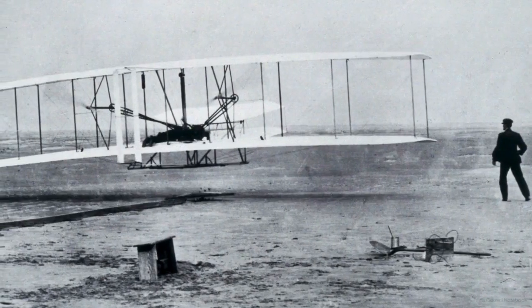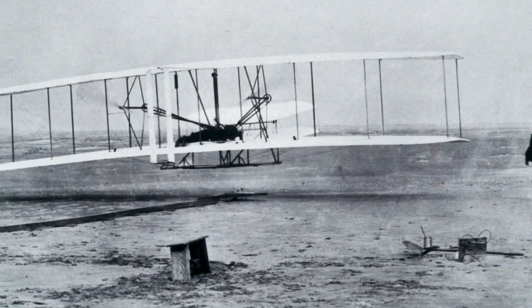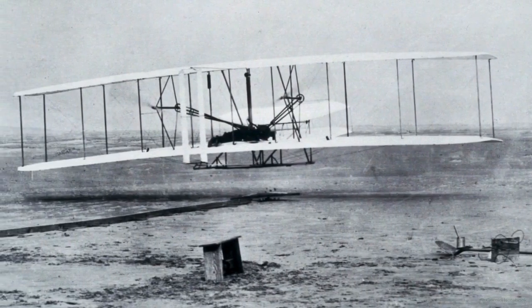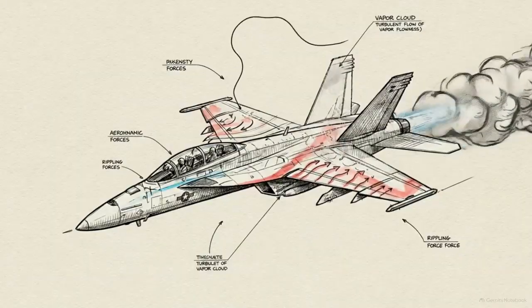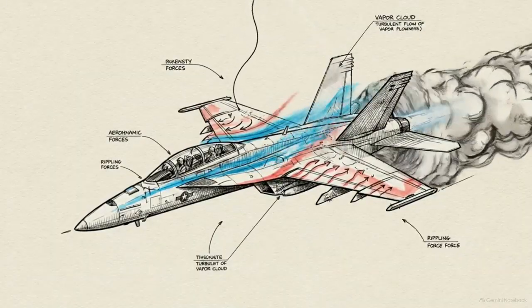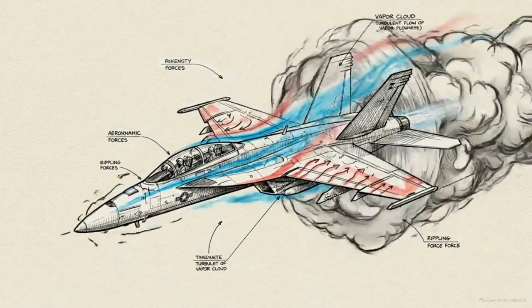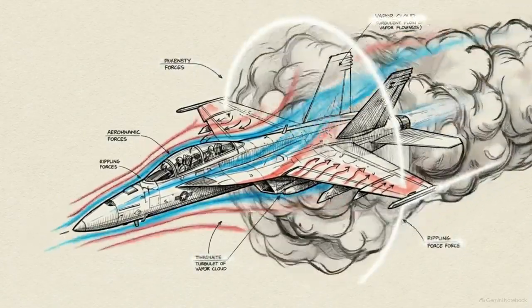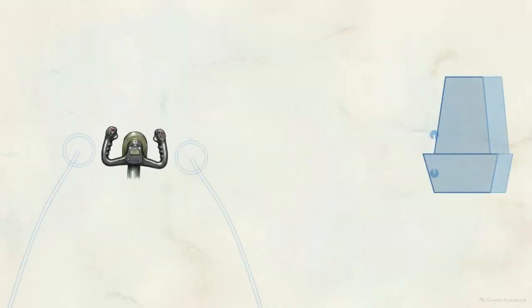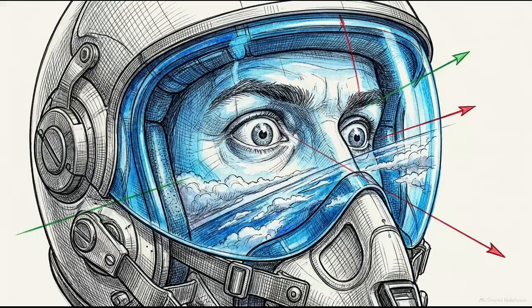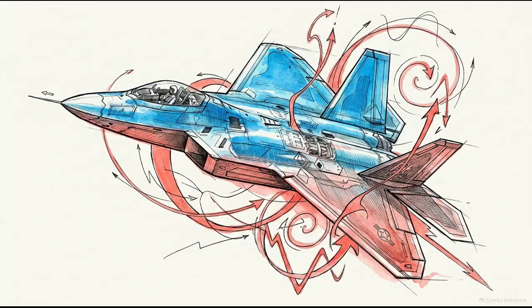In early, lightweight aircraft, this touch was a direct physical struggle, a literal battle against the wind hitting the wings and tail. As aircraft evolved in size and speed, engineers were forced to sever this direct mechanical link to protect pilots from the massive aerodynamic loads involved. This created a new engineering challenge: the need to artificially synthesize a physical control touch that is no longer naturally present. Without this engineered feedback loop, the human brain cannot process the aerodynamic reality of high-speed flight, a disconnect that can make even the most advanced aircraft difficult to control.